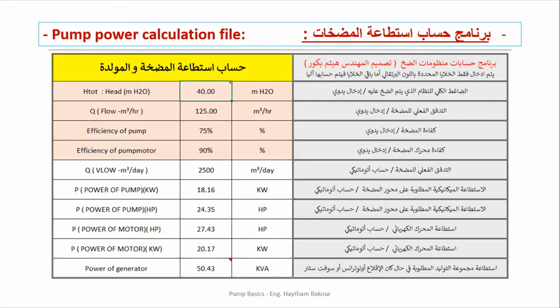There is a question about the pump. Many people, through the contract, usually don't give attention to the specification. One pump's efficiency is 80, one of them is 70. The price difference is not a lot, but we are choosing the cheaper, and then we are losing a lot.